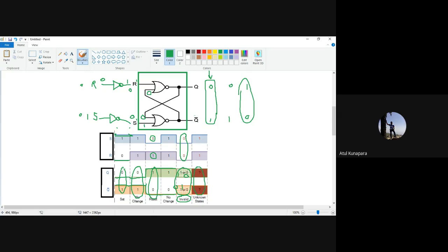Okay. So in short, this latch is the smallest unit of your memory, and it is a sequential logic circuit in which your output is going to be set or reset on two conditions. One is what you are providing at the input side, and second is what is already available at the output side. Okay, so that's the thing about this latch.